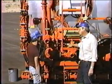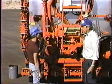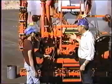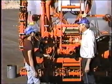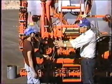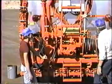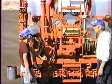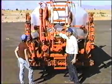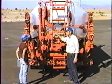Remember, I said that that main equalizer valve is tied directly to the master switch. Let's say the very last thing that we shoot, we're out here on a chip seal, and the last thing we shot just before we parked was a big long taper. Say we're doing an on-ramp to the freeway, and we just shot the tapered part of the asphalt where it comes out onto the concrete. Well, we went across the bar switches on this fancy machine, shut the bar off one section at a time, all the way across the spray bar. The spray bar is all turned off, but the master switch is still turned on.